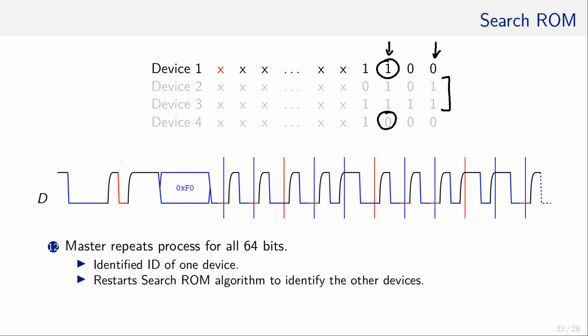For instance, the protocol says that all 1-Wire devices must understand the search ROM command. But other commands might be optional, such as the overdrive command to increase the data transfer rate. If another IC is out of the question, maybe due to the wiring, power, cost or space constraints, a software implementation needs to be considered.